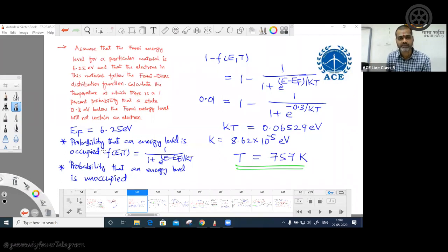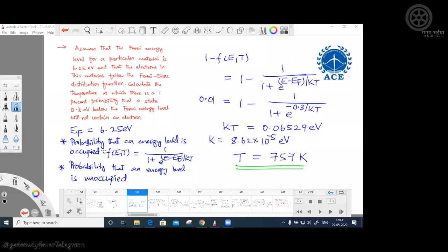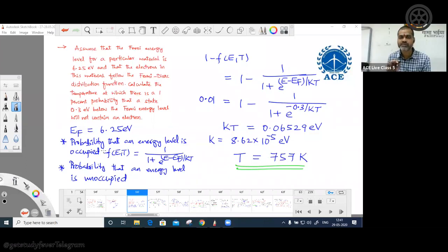Exactly half. When you make the electron move from valence band to conduction band, you are not making your electron move out of the crystal, it is still present. So as a whole, considering valence band and conduction band, how many are going to be filled? Always it is the same. The only thing is, to modify the electrical properties you want to make your electron move into the conduction band, because the electrons present there are responsible for current. Are you getting?